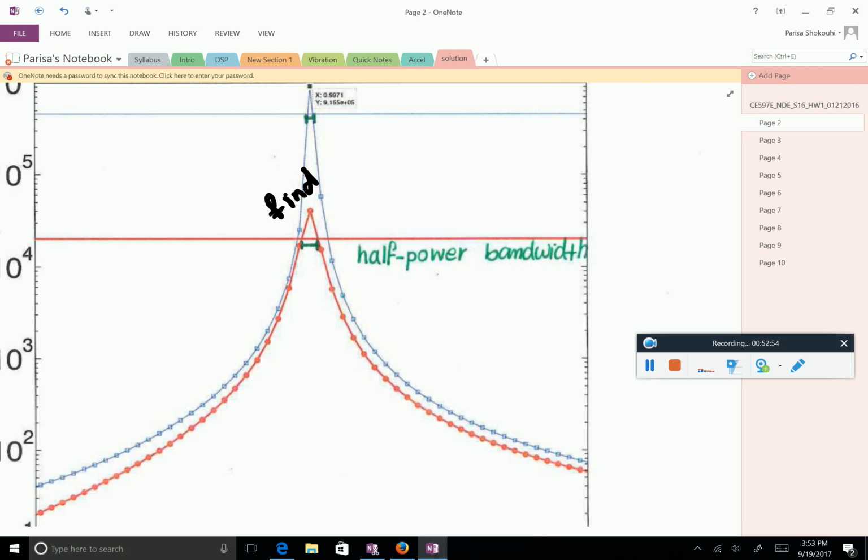Yeah. Can you write out how you use the find function? If you're going to be looking at half the power value, I'm just not quite understanding how to use find. No, just look at the help of MATLAB. So it's like find, if you have your FFT greater than, let's say, FFT peak over square root of 2, something like that.